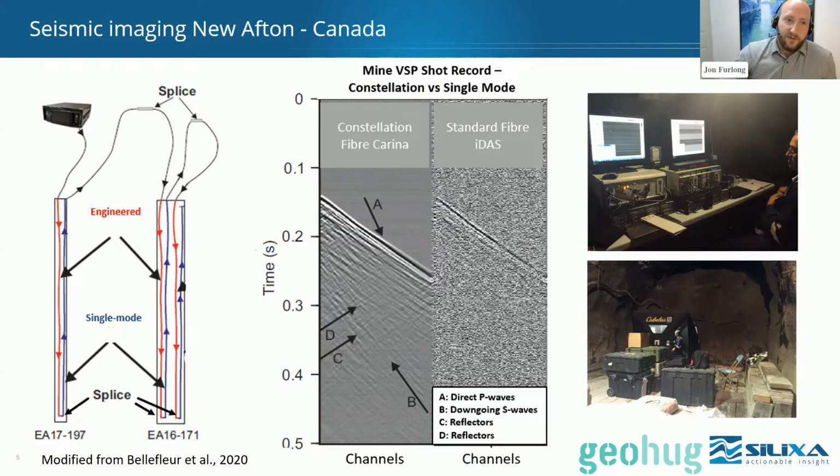So you can see the boreholes over here and a schematic of how we've placed our fiber in these boreholes. Essentially, we can do turnarounds in our fiber at the base of any individual borehole. We place the fiber in these boreholes that are roughly 800 meters in length, and we do fusion splices at the surface so that we can daisy chain multiple boreholes together and make one continuous array. So one interrogator can then sample many boreholes and many kilometers of fiber in that method.